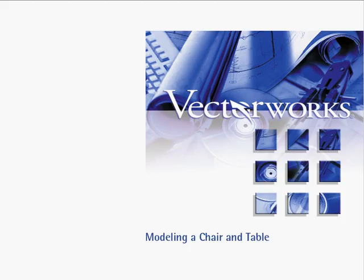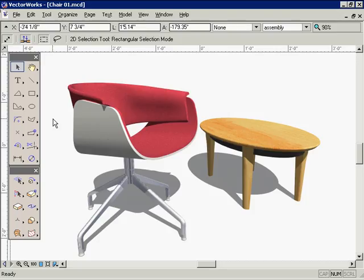Let's look at a few ways that the new features of VectorWorks 10.5 can be used to create free-flowing 3D shapes. I'll create this table and chair using some of VectorWorks NURBS modeling tools. We'll begin by making the seat of this chair. It's composed of two objects and has a fairly complex curved shape.